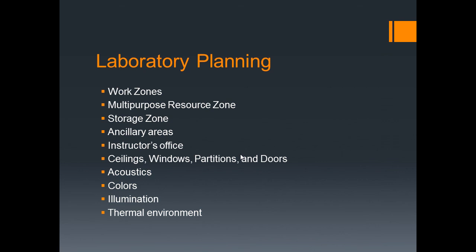Do you have enough space or a set of double doors, or maybe an overhead door, to be able to get equipment in and out? What about your windows? You don't want them at residential levels, because all kinds of things can hit them. Your book kind of gives a minimum of 9 feet to the base of the window. So like that, they're above you, not at eye level.